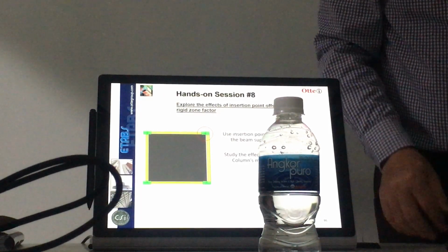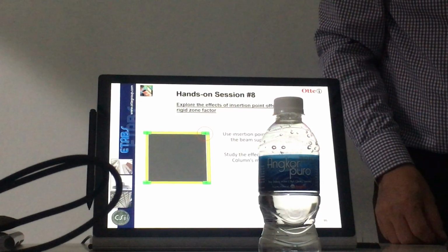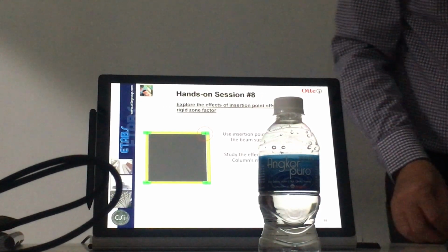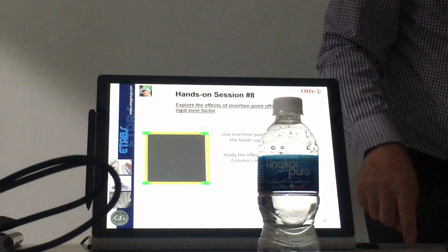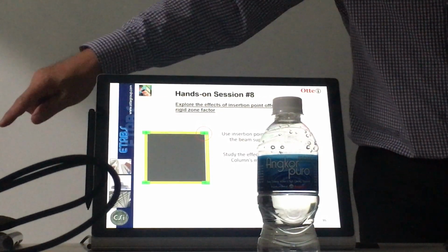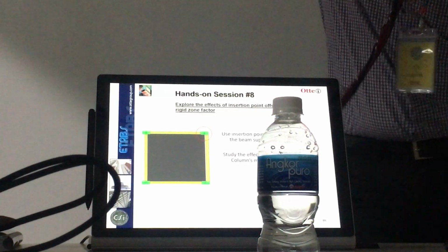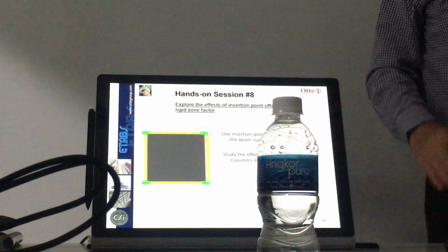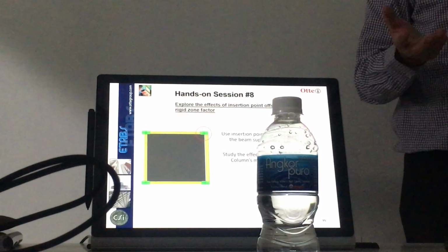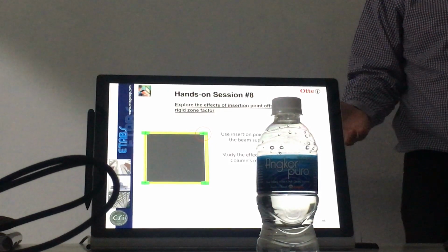So I'm bringing you another concept right now. Don't always think that I must put the column in exactly the same place like the architect one. Because if I do this one here, this column there, so these two lines and this column, they're all not straight line. And then I need to run a straight beam. So you have to do all the offset and all the offset. Chances are, most of the time, you will mess up. The model unstable, cannot run, right?